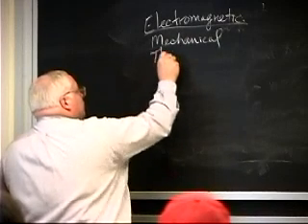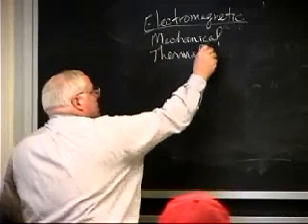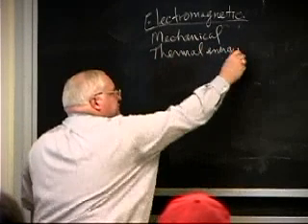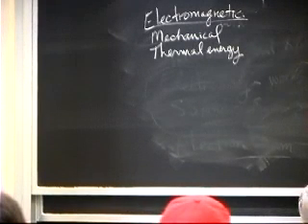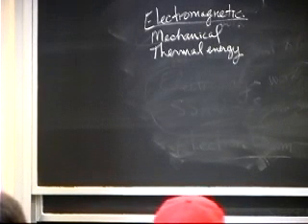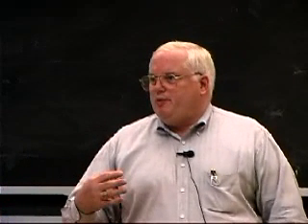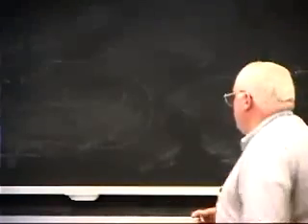I can have thermal energy. A lot of times on composites, if I want to see if there's a flaw, I use the poor thermal conductivity of the polymers, and I heat up the composite on the backside, and I use a thermal imager on the front side, which is an electromagnetic detector, and I see if the heat comes through uniformly. If there's a void there or a delamination, that's a thermal barrier, and I won't see uniform heat coming through if I heat it uniformly on the backside, for example. Okay, so that's one way to use thermal energy.